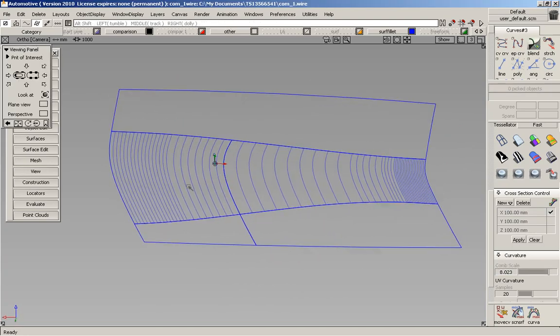One of the disadvantages, however, is if you look at the tangent lines created with this variable radius fillet, you'll notice that they're the same on both sides. So if we want a fillet that has a different tangent line on, say, the bottom, or some type of stylized blend or fillet situation, the surface fillet tool is probably not going to be the best option.